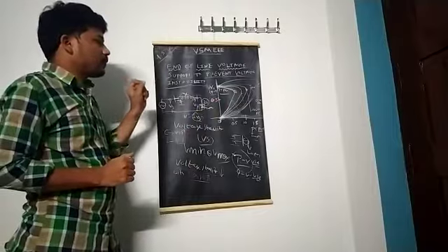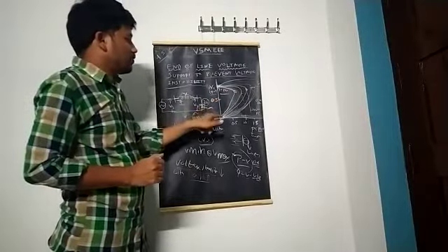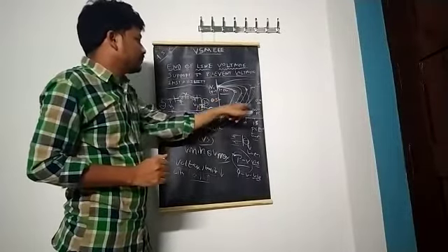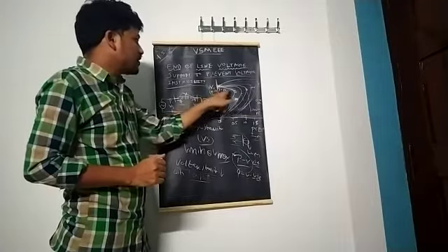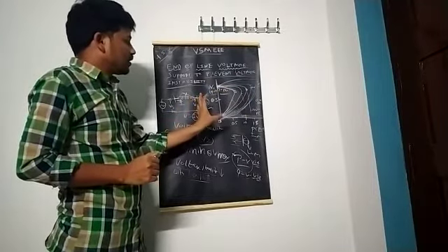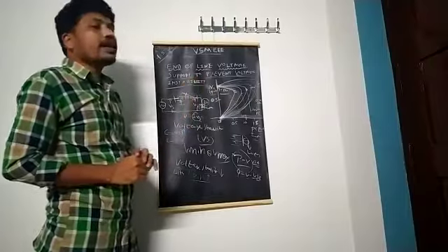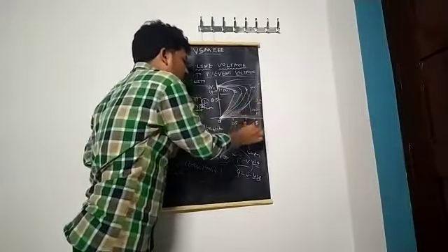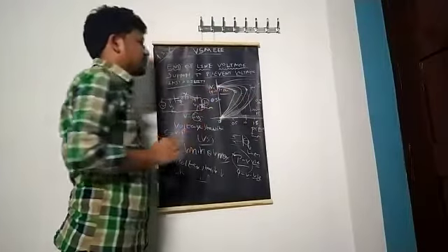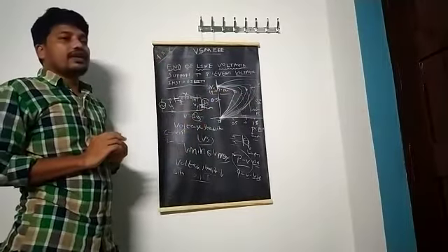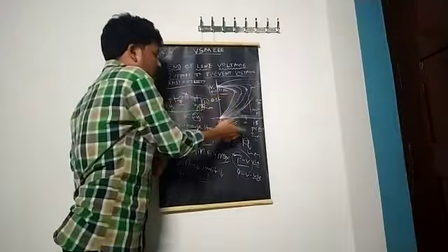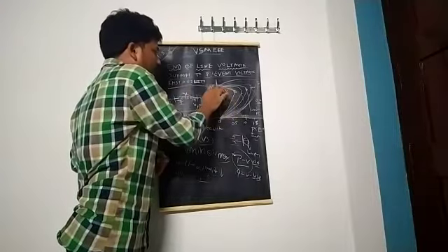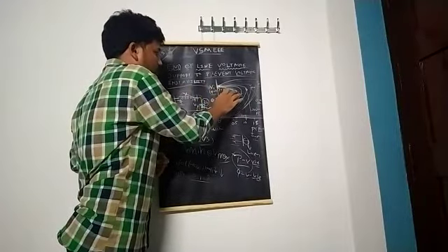This point represents, for various kinds of load and power factor, where the voltage changes. This is nothing but the critical point or nose point. For various power factors and loads, the voltage changes. As the load increases, the voltage decreases up to this critical point. After that,